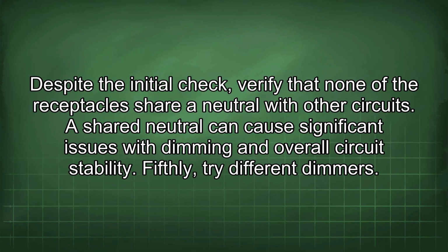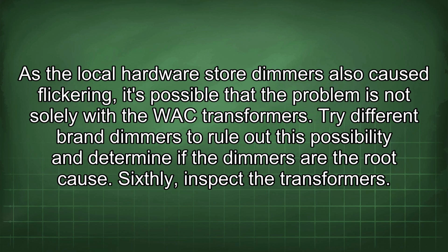Fifthly, try different dimmers. As the local hardware store dimmers also cause flickering, it's possible that the problem is not solely with the WAC transformers. Try different brand dimmers to rule out this possibility and determine if the dimmers are the root cause.